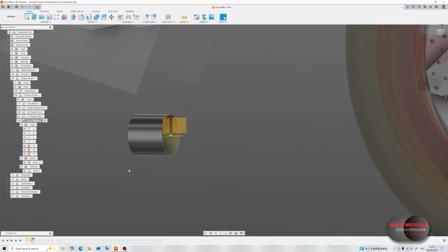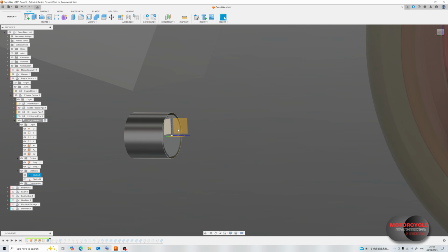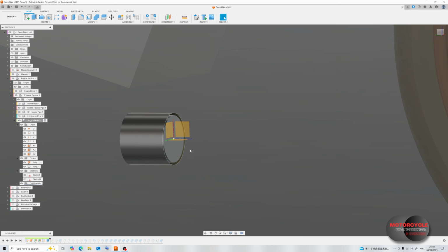I was considering modeling this in surfacing, and I did have a little attempt, but I found that there were some issues trying to bring those surfaces together and fill in certain rounds. So it's something that I would have to practice with a bit more to really make something worth sharing. But what I did find was using solid modeling would be easier for joining these together.